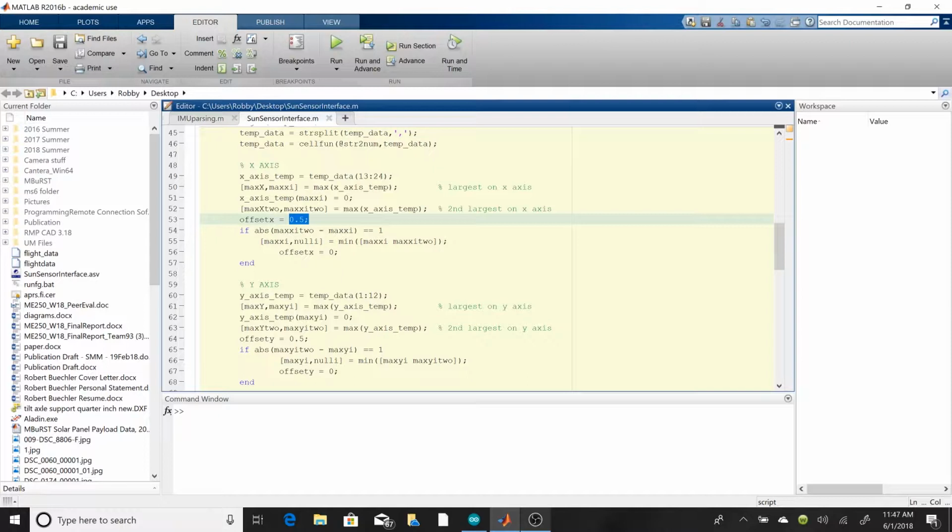So the distance that we use in our calculation should be the distance from the center of the array between photoresistors numbers 6 and 7 and the midpoint in between those two resistors that the light is hitting. So basically that is what offset takes care of: it tells us whether we want to go to the center of a resistor or in between two different resistors.